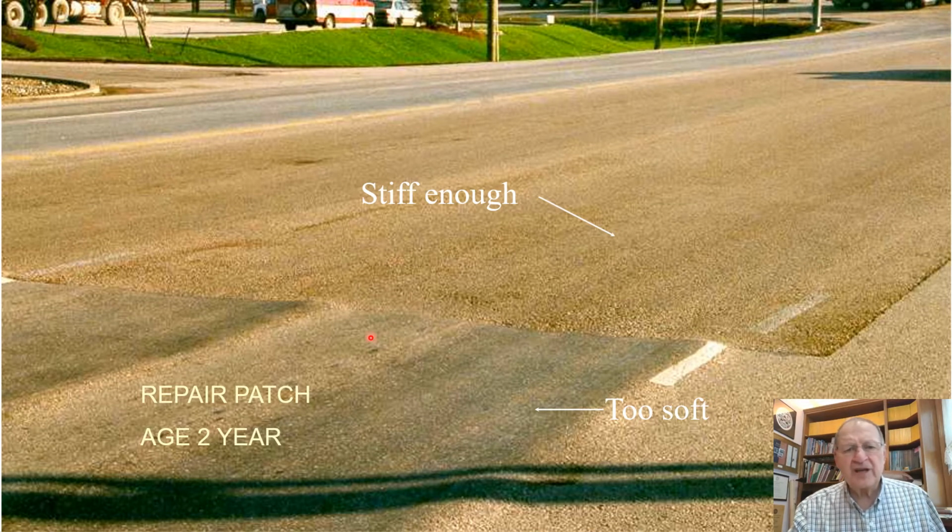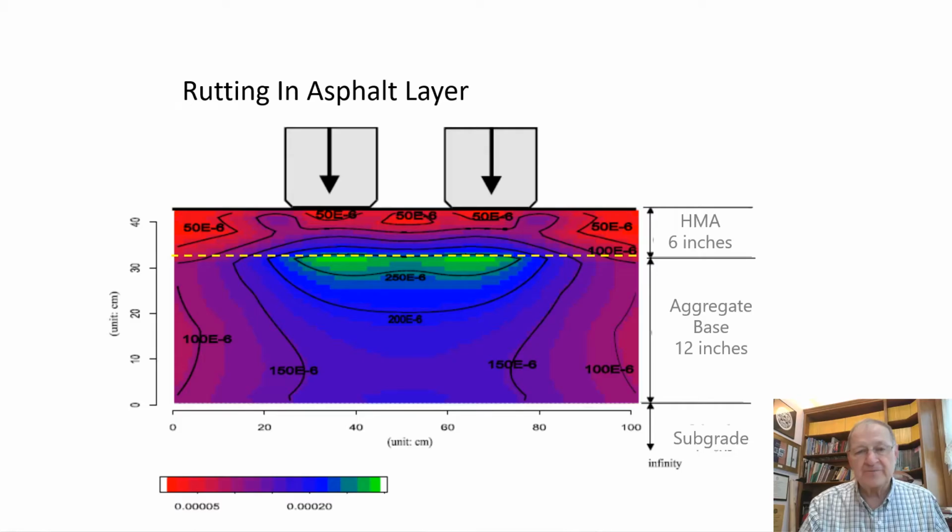So what the contractor did was build a trial section right before the traffic light, using the AASHTO specifications for this, which, by the way, predated the implementation of SuperPave by the city, but the DOT was using SuperPave. And so the suggestion was, why don't we build this using SuperPave specifications? And that's what was done. After 2 years, we came back and found almost no rutting anywhere on this. And of course, the rutting that we see on here is about 2 to 3 inches.